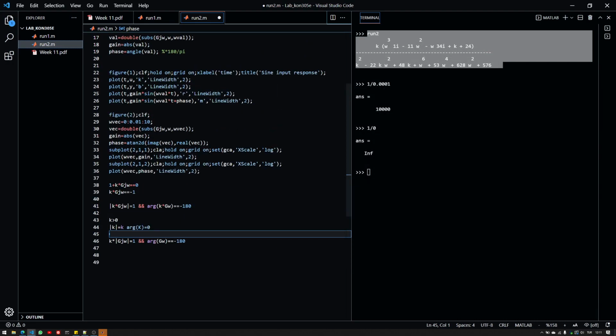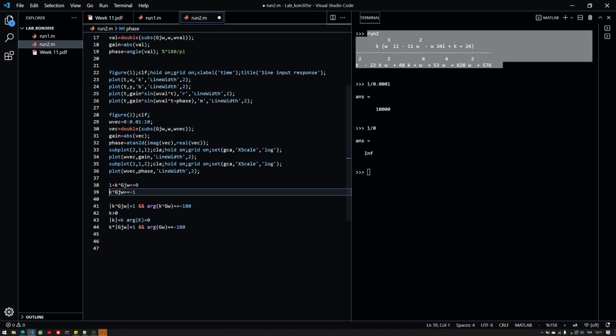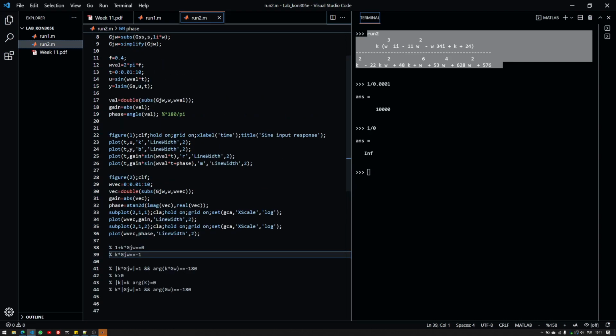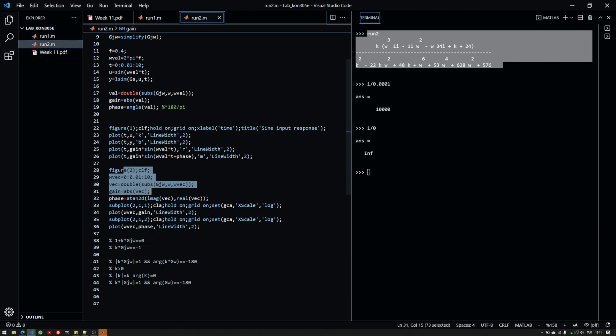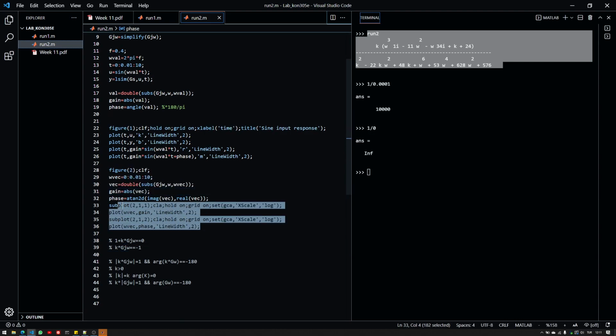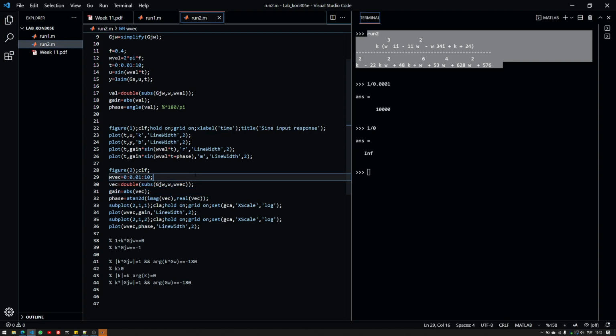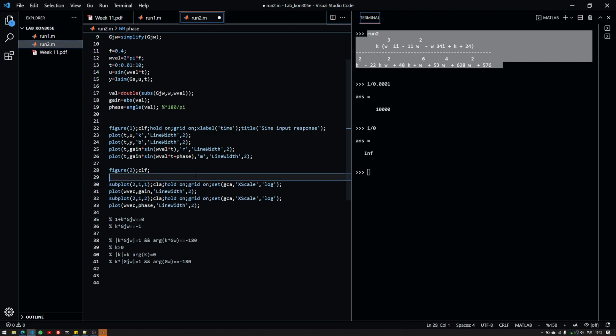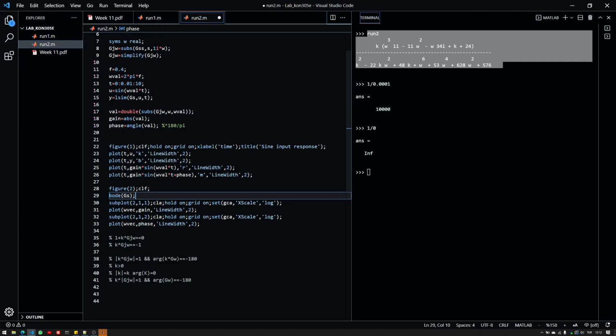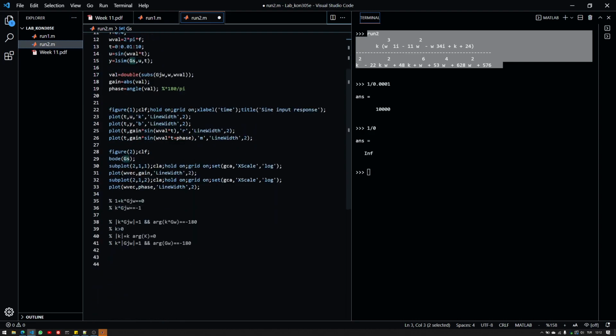So of course we will, let's say, yeah, let's have these here. Let's comment these out. Now, before I continue, of course, instead of using this calculation on your own, it is possible to skip this calculation and call the bode function, and it'll give it to you. So instead of doing this, let's get rid of that. Let's call the bode function here, gs, based on gs, this one here. And as in the case of the step function, it'll give you the necessary outputs.